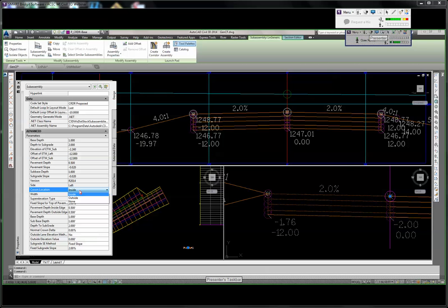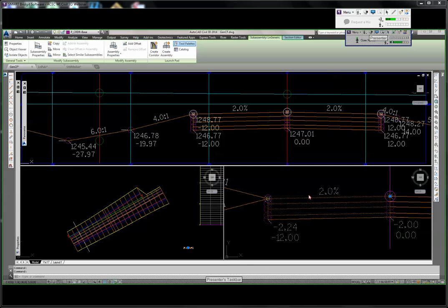If you are doing what I've got here, in fact, I'm going to change my slopes back to -2 so I have a regularly crowned road. If we are working from a crown going outward, that's where we're building our crown from, the inside point is good because that is actually where you're attaching it to the roadway design. If I chose outside, that actually means that I'm starting here, the crown point is actually here, and the lane is going backwards. That would put the crown point at this location, for a lane starting at your edge and coming back.